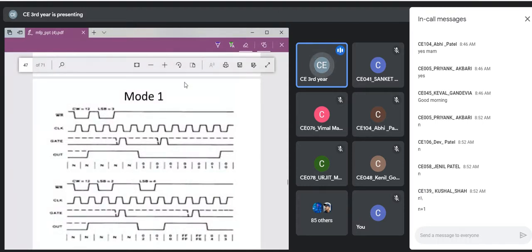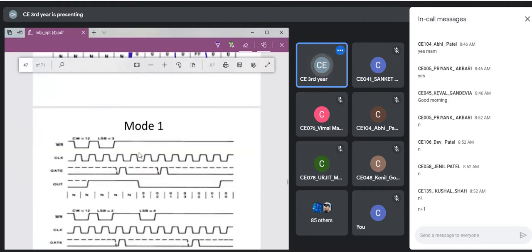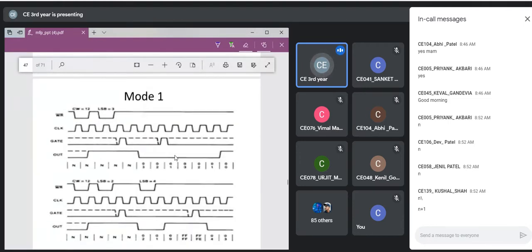Okay, now another case, if you consider. Before the out goes high, ideally what should happen? The out should go high, because my 1 is reached. Now the next count will be 0. But before my out goes high, my next trigger came. That means in this clock cycle the next count must be written, and that's why the next count is written, and the countdown is started, and when the count reached 0, the out went high. So actually I got this extension because of this trigger.